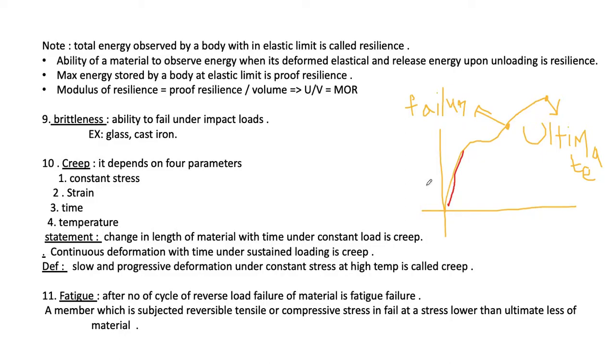Creep is the most important topic, and in many competition exams like GATE, questions are often asked on creep. Creep depends upon four parameters, which must be kept in mind: constant stress, strain, time, and temperature. The statement is that change in the material with time under constant loading is creep. In the definition, when time and constant loading appear, that is compulsory for the definition of creep.